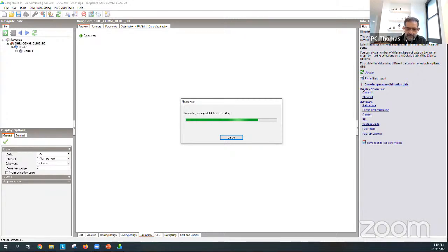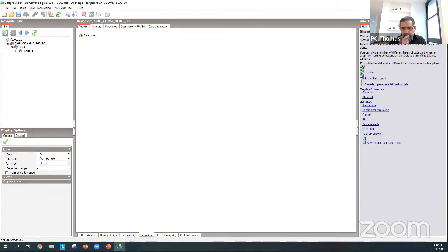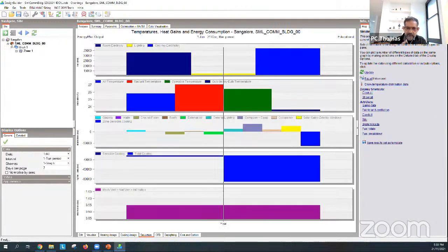So most of the analysis we do is not really very helpful unless you do that control strategy to switch between an air-conditioned mode and a naturally ventilated mode, what we call the mixed mode kind of building, and put an explicit control strategy to say when that should happen, and when it's in natural ventilation mode, what should it be doing, okay?